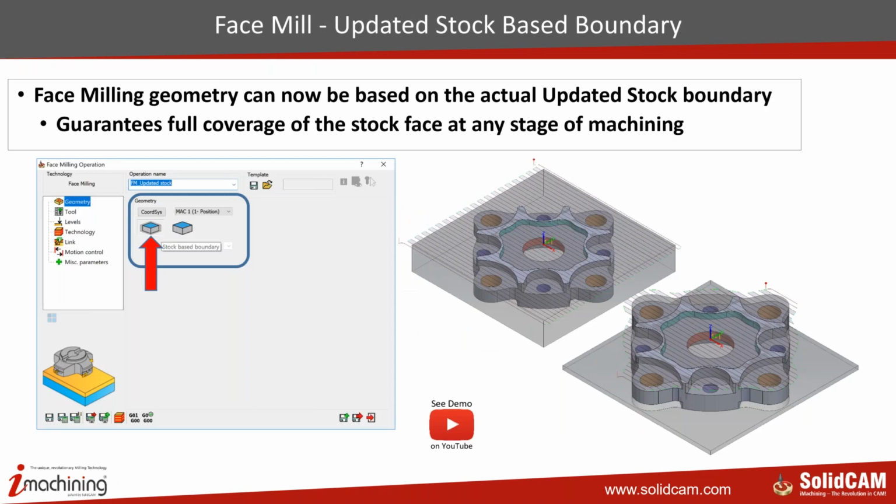Another new function is the updated stock based boundary inside face milling operation. Now when you go to face milling, you have two options. One is stock based boundary, another one is the target boundary. By default, it is always set to stock based boundary. Depending on the stock condition, the boundary will be updated automatically.